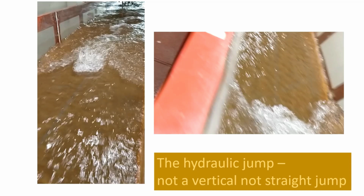Okay, so we're just going to look a little bit more in detail at the hydraulic jump. You'll see in this one we've got a shape that's like this, where I've talked about it in the lectures as though it's straight across the channel, and theoretically it is, but there are some friction edge effects here that are causing this shape. So we need to take that into account when you're writing it up. If there are some errors, there's one for you to see.